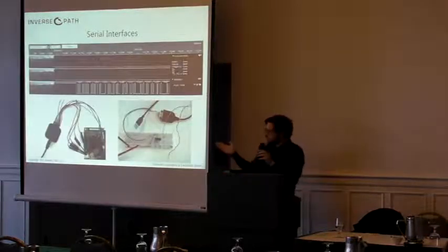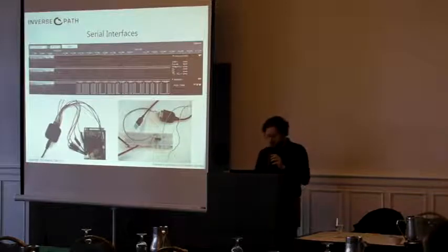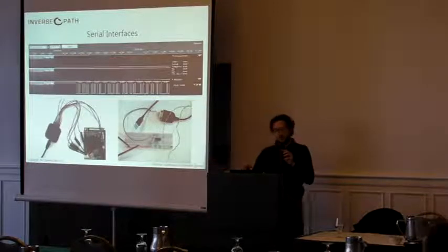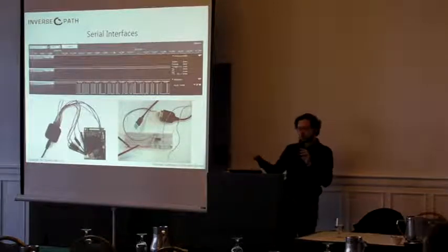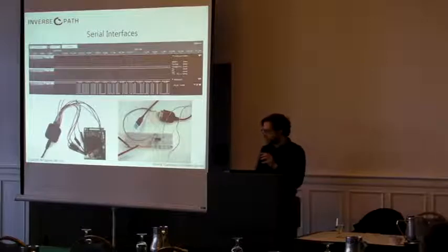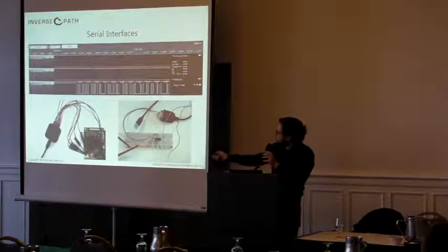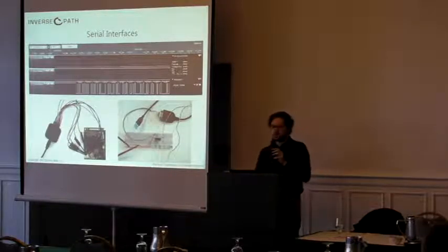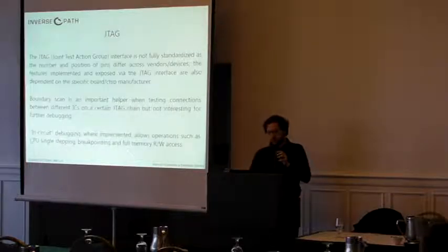This is an example of a logic analyzer attached to a board, very crudely, it's not too refined. With the software that comes with your logic analyzer, most of the time you can also decode on the fly what's there. So it's super easy.